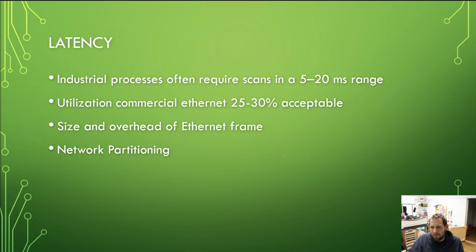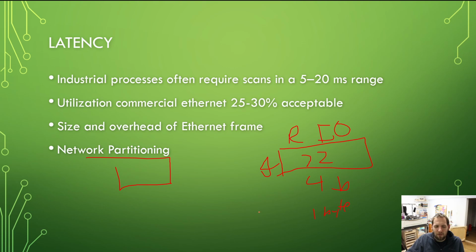Right. If every time I have my remote I/O here, I'm gonna go with RIO, and that has 32 devices on it. Right, I need to send 4 bytes of information every time I need to communicate back to the PLC over here. Well, I'm only going to say, okay, here I have 32 inputs or whatever. I'm only going to send the things that have changed. All of a sudden, maybe now I'm only sending 1 byte of information every loop of code type of thing. So that decreases our network traffic. And again, you may think one device doing it, not a big deal. If you have 100 devices on your network all sending 4 bytes, that's a lot more information to be sent. So that is going to be a nice big key.